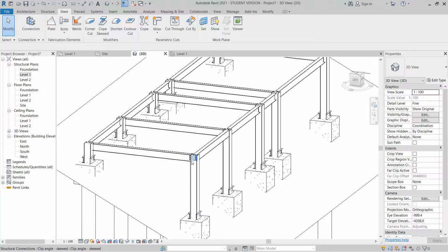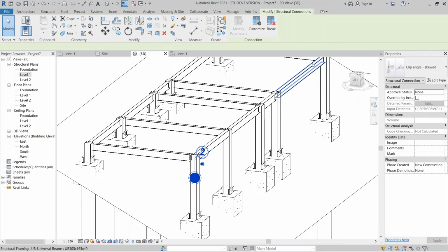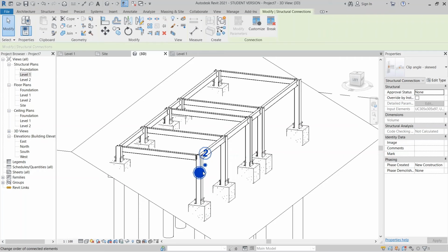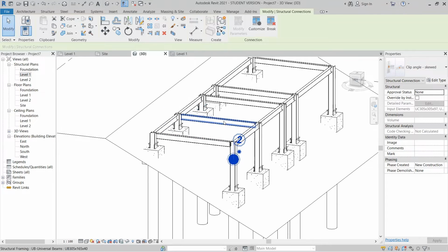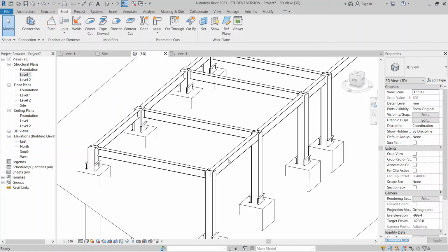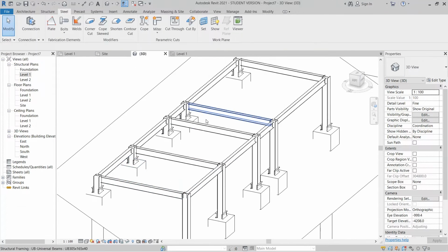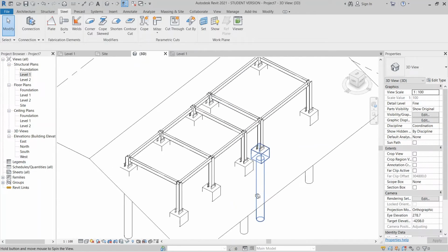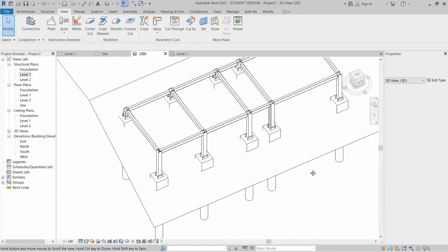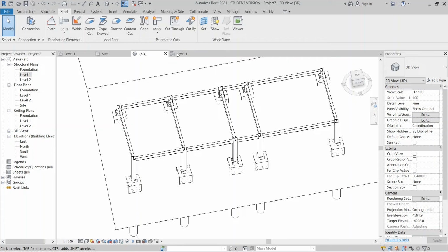And for this one, my suggestion, you just select here, then copy same as your base plate there, and this one also. And after you copy all, you can select all elements, then you can mirror from here until here in the same method. Okay, so now I want to load another column from the top there. Before I load my column here, I would like to add some beam system first. Go back to my level 1 here.